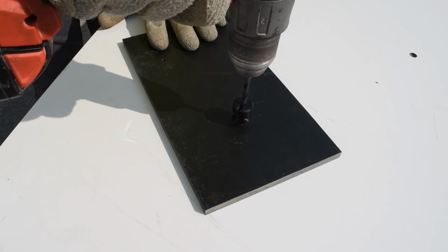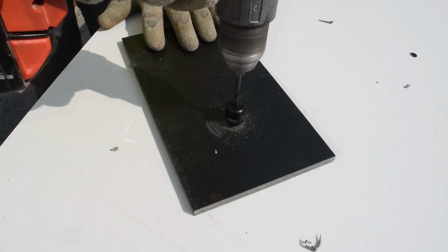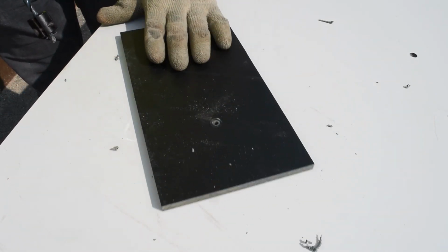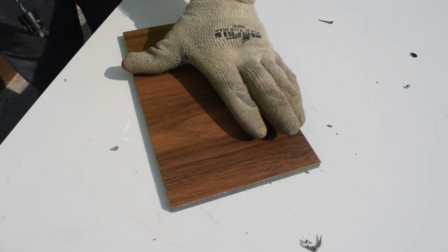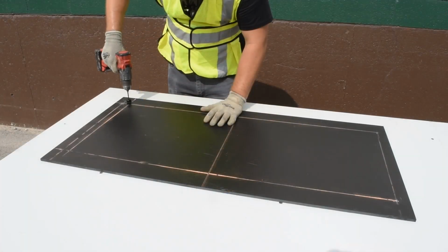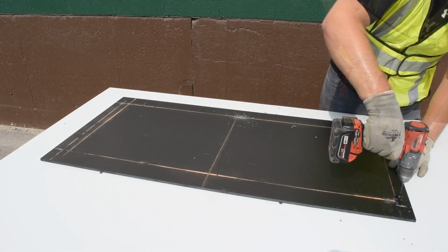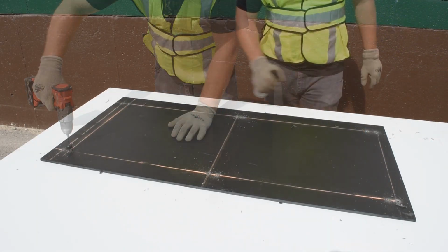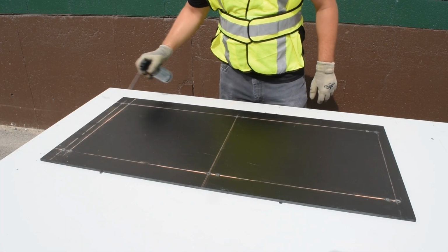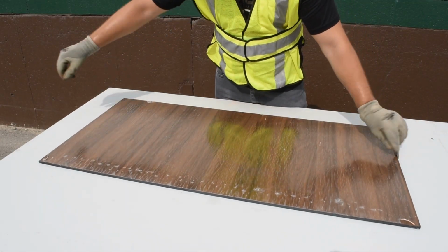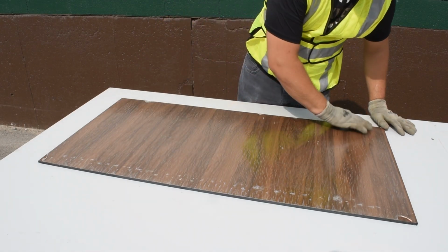Make a practice drill on an extra panel to make sure the depth is set correctly and that there is no drill through on the face of the panel. Proceed to drill the required holes on the back of the panel. Clear any debris from the holes using compressed air. Finally, check the face of the panel for any possible drill through.